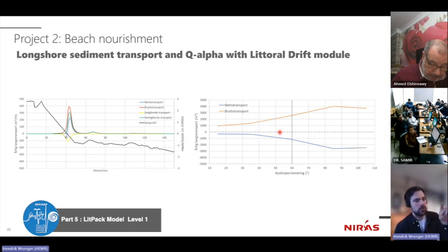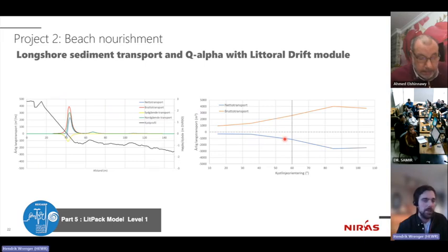And I get these sort of zigzag coastal profiles where each beach subsection actually develops a stable beach or in the equilibrium direction. And then maybe with groins, I can actually stabilize my beach. But that's not an option here, right? We will all agree we cannot rotate the coastal orientation by 45 degrees with any structures.